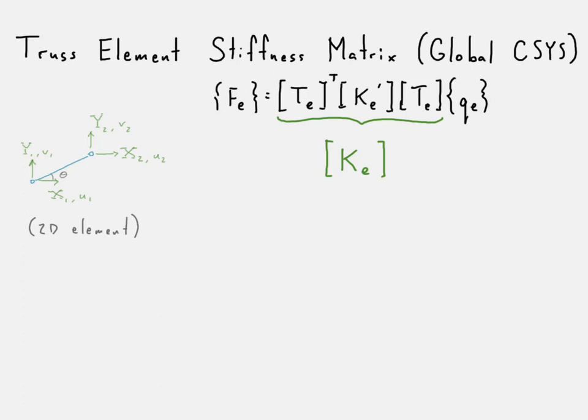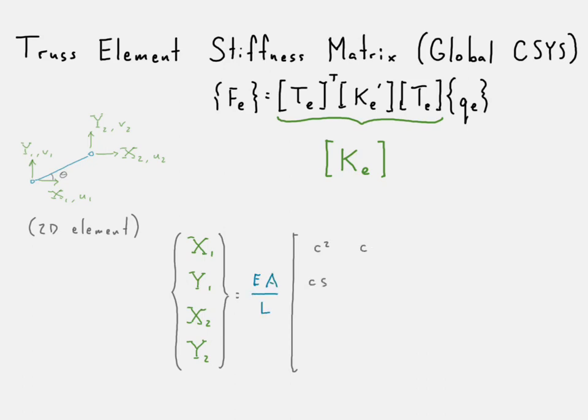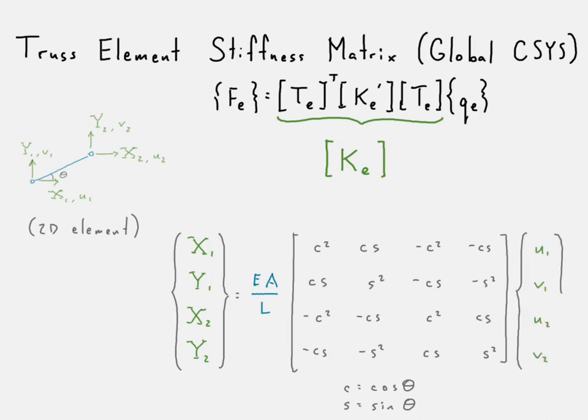So there's our two-dimensional element. We're just going to go ahead and write out what each of these terms mean as we multiply everything through. It's common that you'll see this representation written as follows, where each of the C's represents a cosine and each of the S's represents a sine. That's a very common form. I will personally choose to write it like this because that form will work in 3 dimensions. It will work for frame elements, any line element. So I'll use that to be consistent, but for a shortcut, you could also use this form that you have down here.